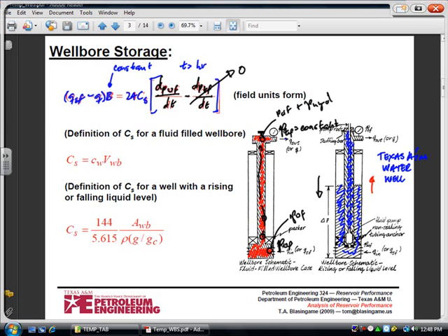And there's an old example where that could be 10,000 psi. If this is 5,000 psi and the well's 10,000 feet deep, we take it upstairs, it's 5,000 pushing on 10,000 feet. So at the bottom, you get 5,000 plus the hydrostatic.